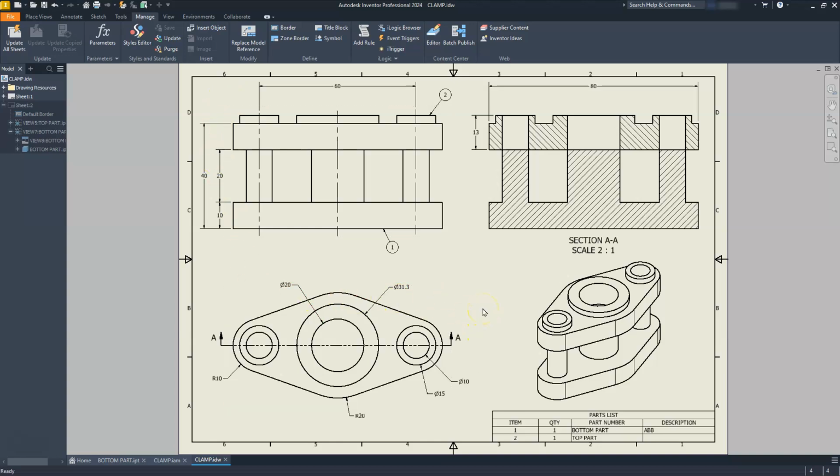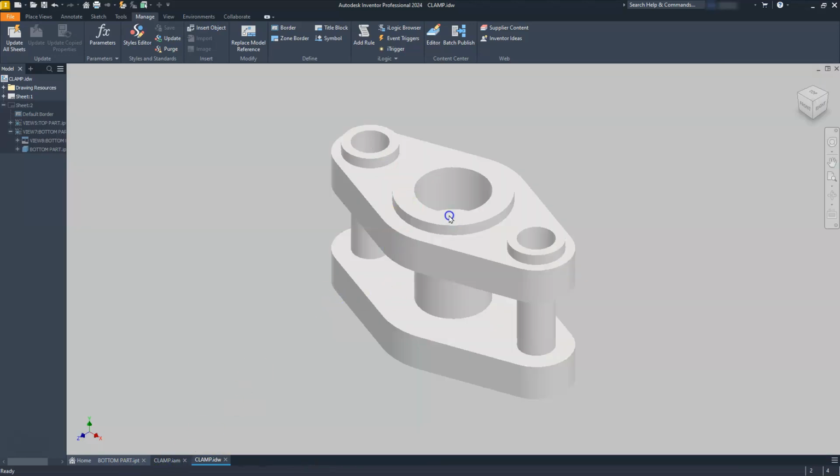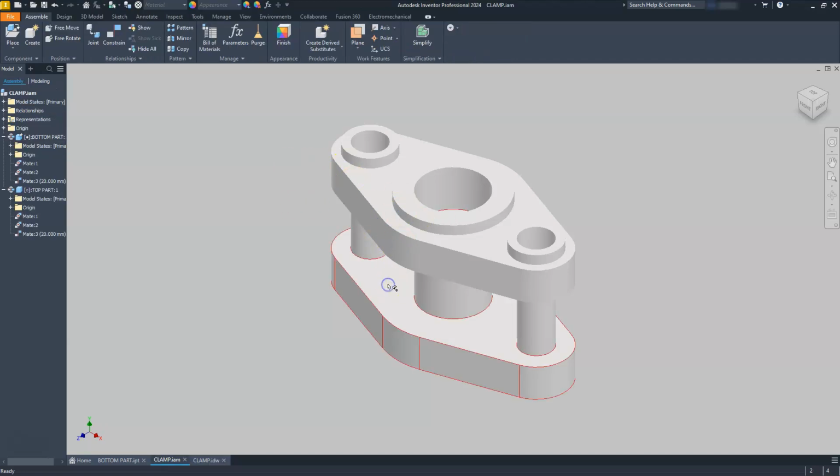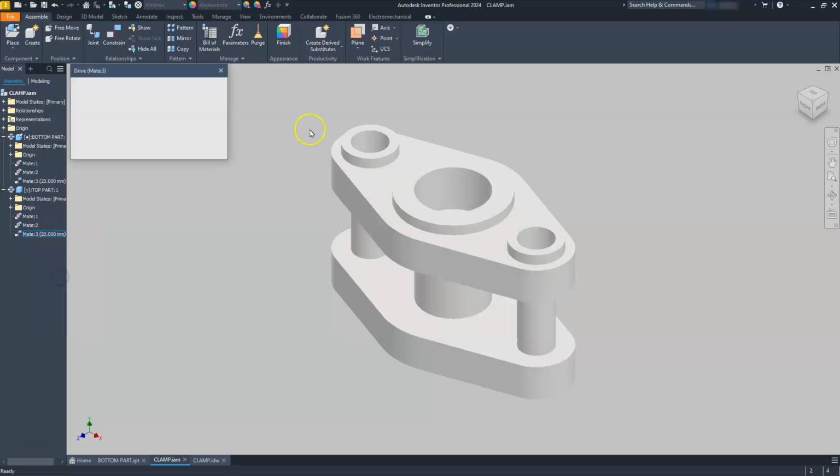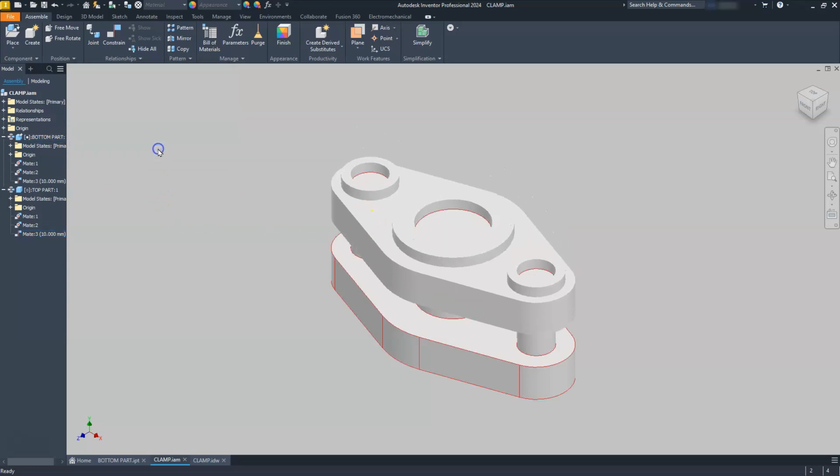Okay, so the key takeaway here is that anytime you're using Inventor, it's a lot easier to do things. And this is one of those things that I wanted to tell you about. Say I went to this one, and we're going to adjust the height of this. Underneath that drive constraint, I'll select here and go to drive constraint. Instead of making it start at 20, we'll make it end at, let's call it 10. Let's drive that constraint so you can see that it did drop down.